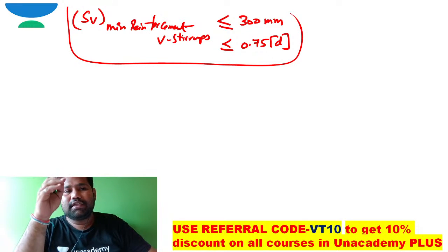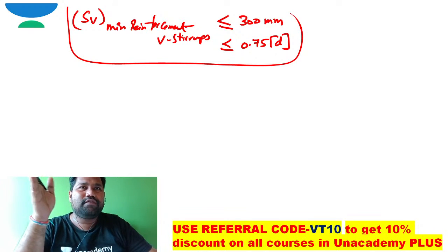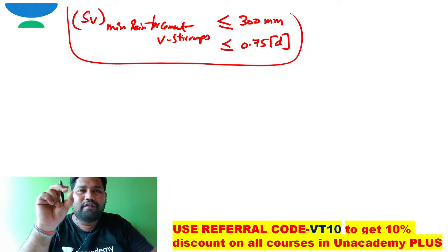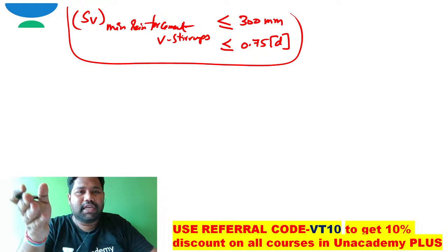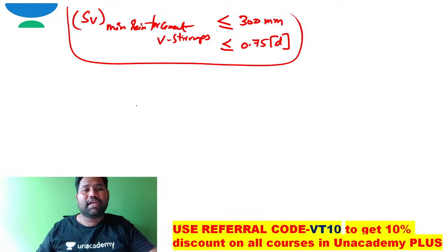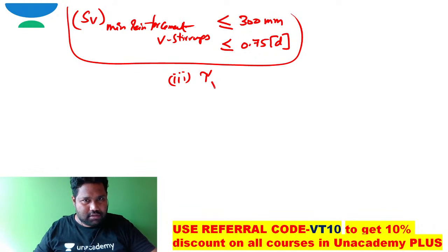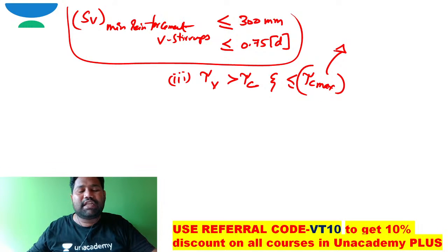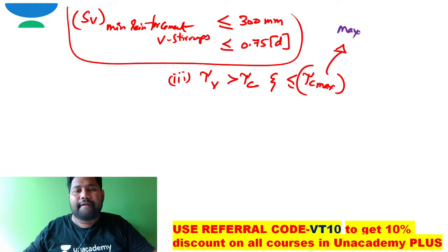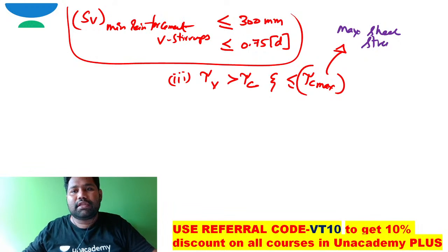Some people will say, sir, this is how you design the shear reinforcement. You fix the diameter and number of legs for vertical stirrups, work out the spacing, and compare the spacing. Now, coming to the third condition, when the developed average shear stress tau v is more than tau c and less than or equal to tau c max, this tau c max is the maximum shear strength of concrete.